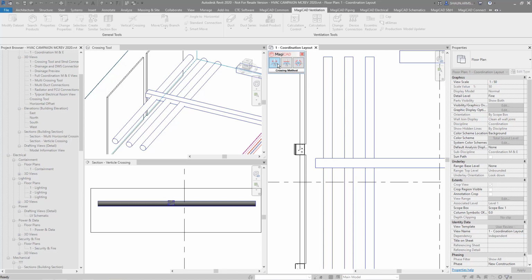This 2-click crossing method, you will have to determine the length of duct that you want to cross over. Just to make you aware, this is available in piping as well. After you've selected your 2 points, you will be given a little marker, and then you'll be given another alignment floating toolbar. This then gives you the opportunity to go over the top of an object, at the center of another object, or at the bottom of an object.